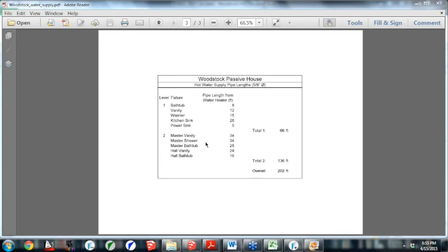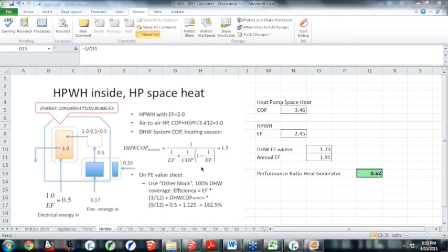Yes, thank you, Dan. So Dan was the CPHC on this. Okay, so the foundation walls, some of the things differed a little bit from the actual project. I thought that you were changing to 6 inches of foam under the slab instead of 10. And I knew the solar heat gain was different on the south windows, but because we grouped them all together, I used the medium gain window.